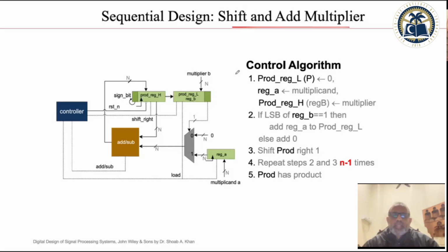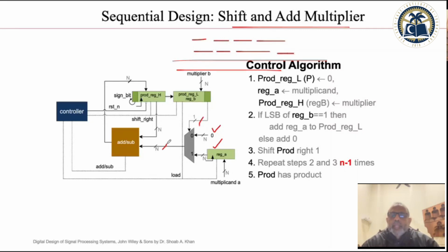So like we do multiplication, you have bits here and bits here. You look at this bit. If this bit is 1, you have the entire number as a partial product. If this bit is 0, you have 0. So this bit will decide whether you will have 0 or the entire multiplicand as a partial product. And next time, once you have generated a partial product, you have to shift it to the left.